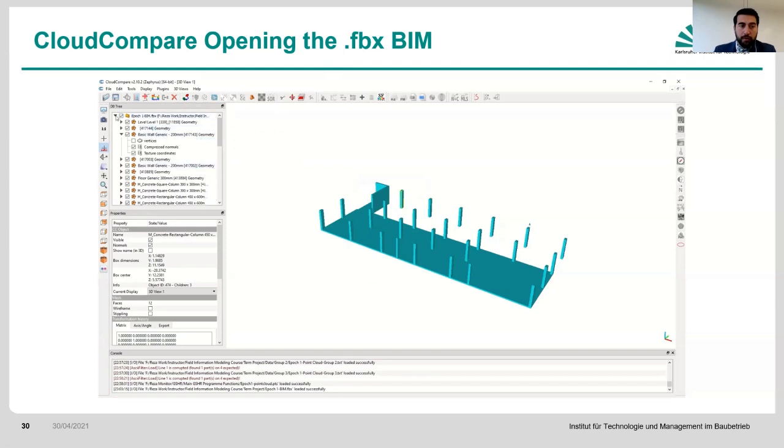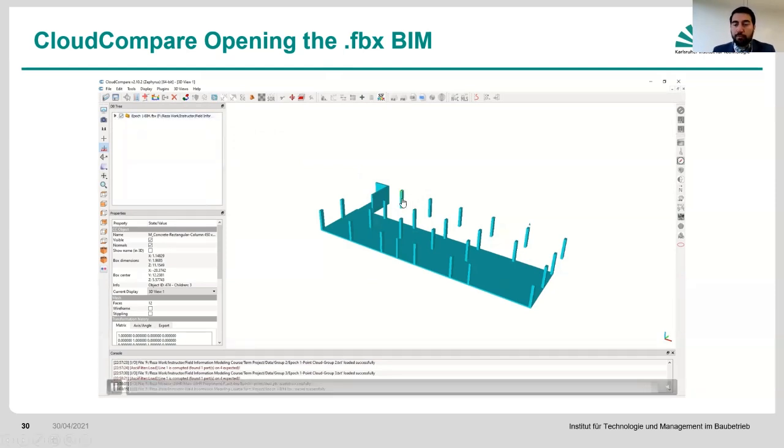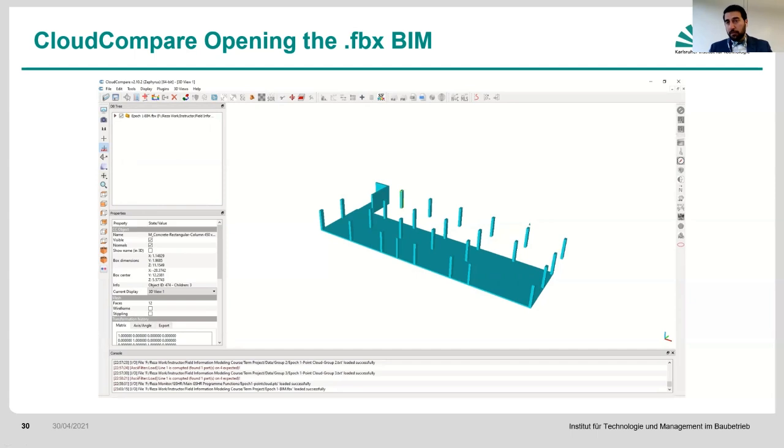So, for instance, for a cube or a rectangular prism like we have here, you would expect 4 surfaces surrounding it, and then 1 top and 1 bottom, which is going to be 6 surfaces, and then twice as much as that, so it's going to be 12 triangles that you're going to see. And sometimes you're going to see a bit more, because it might not be a full rectangle, or it might change in a particular area, so it adds a bit more triangles there. But for the most part, that's how it is. So this is the mesh.